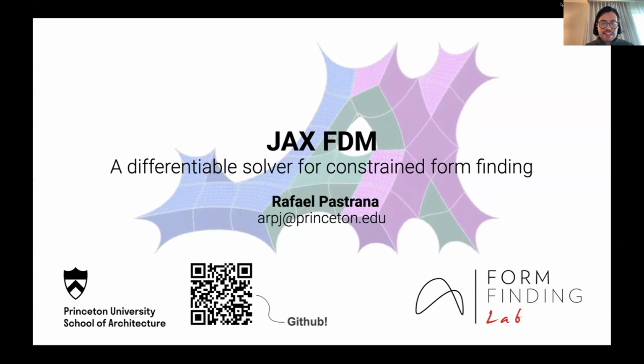And so this is amazing because with a numerical method like this, for a fixed graph G, we can change different values of the parameters Q, for example, and then we can get a plethora of different shapes. Like even these very funky, funny looking ones like the X3, which despite its appearance, is actually another compression only structure. And just for clarity here, we are representing the values of the force densities with the colors here in the Viridis scheme with the color bar.